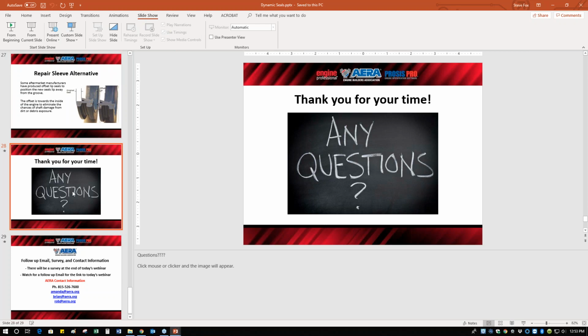I think maybe they're talking about the seal surface of a journal, like a crankshaft rear journal surface, and they're wondering if you machine that, can you still use a regular standard seal? Oh, okay. You're reducing the diameter. That's kind of how I read it. Okay. If that's the case, yes, you can.